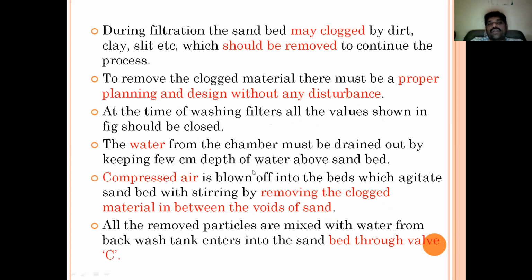Compressed air is blown into the beds, which agitates the sand bed. Agitation, mechanical stirring, removes the clogged material from the voids of the sand. While we are blowing air, we are just agitating the sand granules. By doing so, the blockages in the voids will be released.